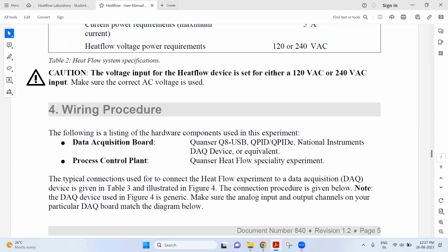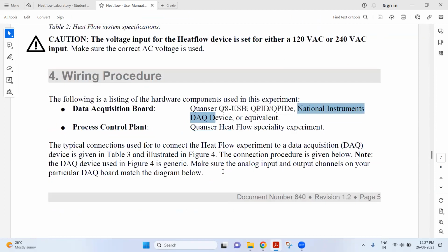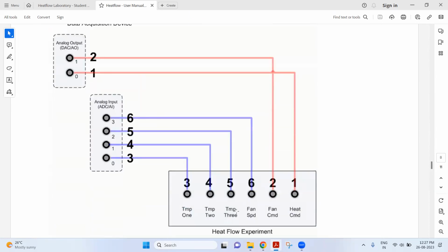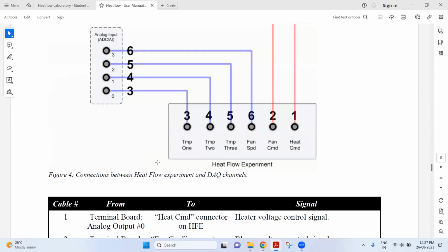Data acquisition, this one, the NI data acquisition system. It basically measures all those things, analog to digital, right? Yes, there must be a DAC and ADC, because that's how things operate. Most of the values we get from these sensors are analog, so we have to convert them to digital, and then you can read all that data from the computer and generate the result. Most of the things with sensors, we get analog data, then we convert it to digital, and then we can do simulations. Yes.